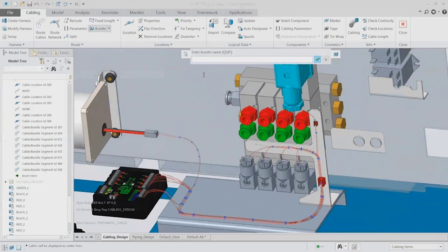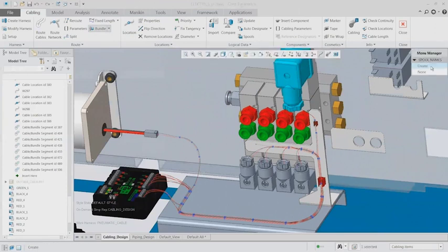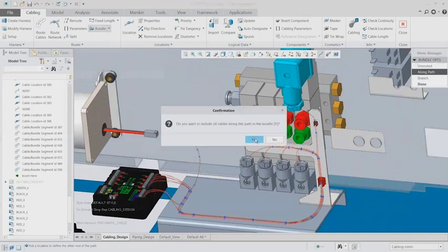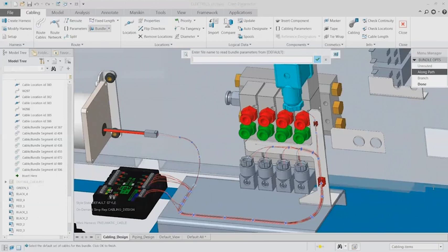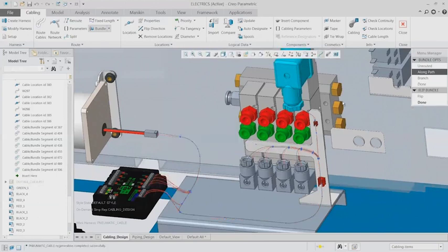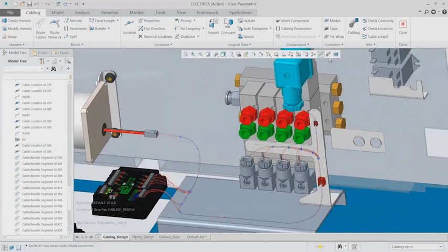So now we want to add some of the extra stuff in. One of those things might be bundling these up. I want to create a bundle for this particular cable harness that I have. There's a few options we can go through in applying this, but it's basically going to try to do exactly what the cable did. We just choose some simple references on a network or on a particular cable. In this case, maybe choose all the different cables that I might want to include. Maybe some of these I don't want to include, so I could just go through and checkbox them if necessary. But then this is going to apply a bundle at the exact points that I had selected.